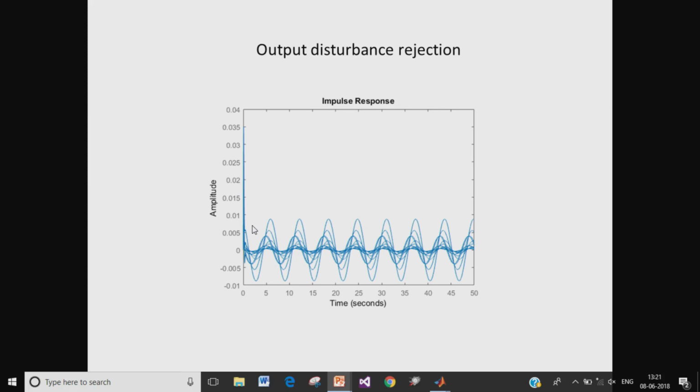So, although we desired 10% leakage or better, we have managed to do much better than what was expected of us, and the amount of leakage that we have of the output disturbance to the output is merely 1% at 1 radian per second. We can also perform this test of the output disturbance rejection at other frequencies up to 5 radians per second, and what we will see is that even at other frequencies the output disturbance has been suppressed by the desired extent.